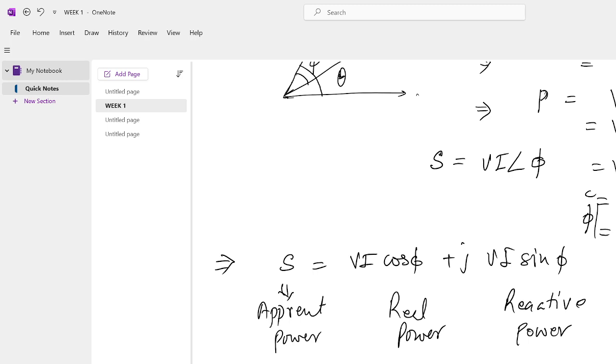Whether we are going to have a resistive load, an inductive load, or a capacitive load, or a combination of resistive and capacitive, or anything. We do not know the nature of load. A transformer is a static device which is only used to step up or step down the intermediate voltage levels. So it has to supply both active and reactive power depending upon the nature of load. Okay, so next question.